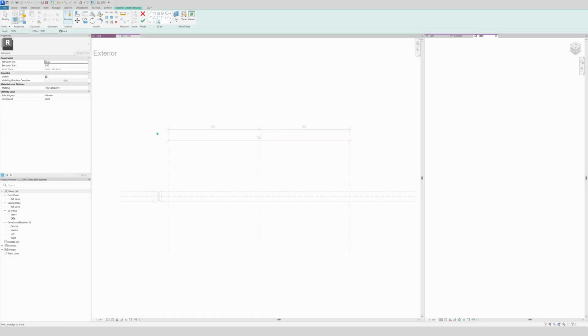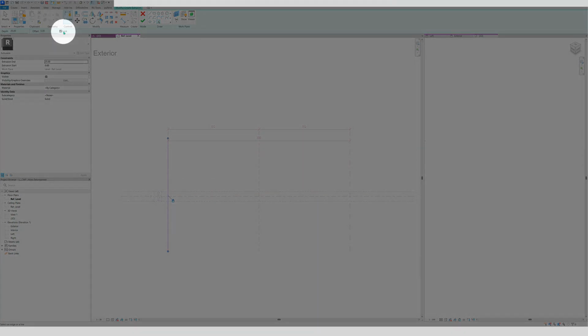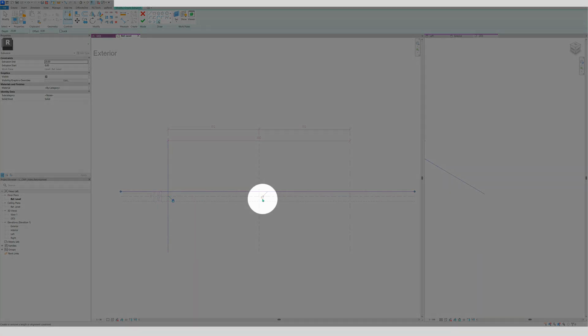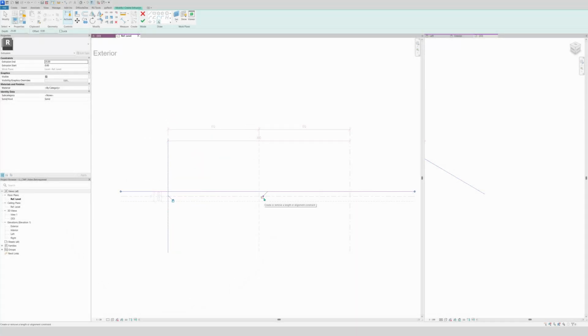That means if I hover over it, right here, I have a reference line and it will immediately lock. See my lock icon. If I don't check this box and I click here, see the lock icon is open, and this one is immediately closed. And then you need to manually lock it first, but I will leave it on. So lock right here and right here.